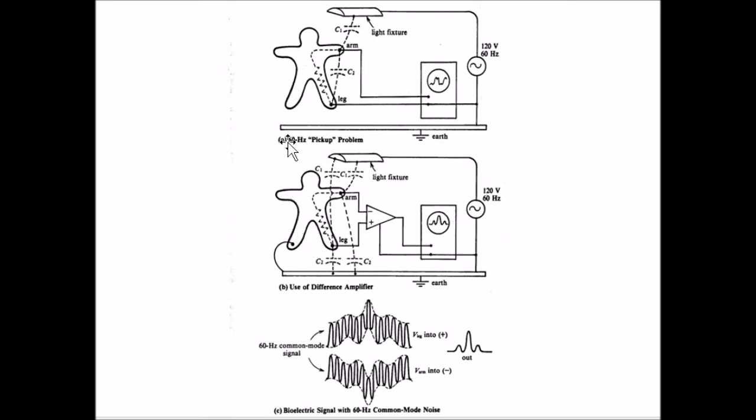But look at this earth rod. As I said in the previous class, if there is no proper earthing, it will create hazards. Which type of hazard? A shocking hazard to the patient. So all the beds and electrical equipment will be properly grounded, and that grounding should be maintained at a very low resistance path, less than 1 ohm.